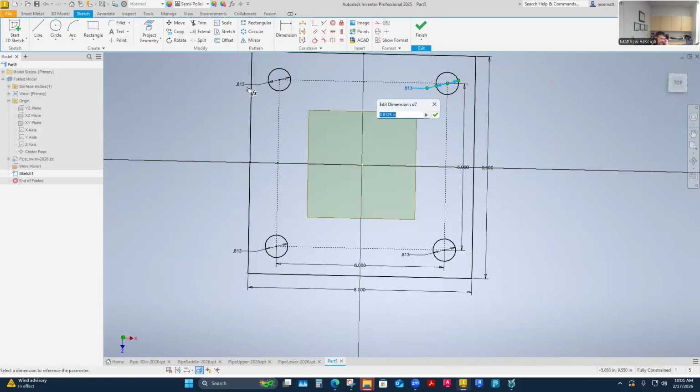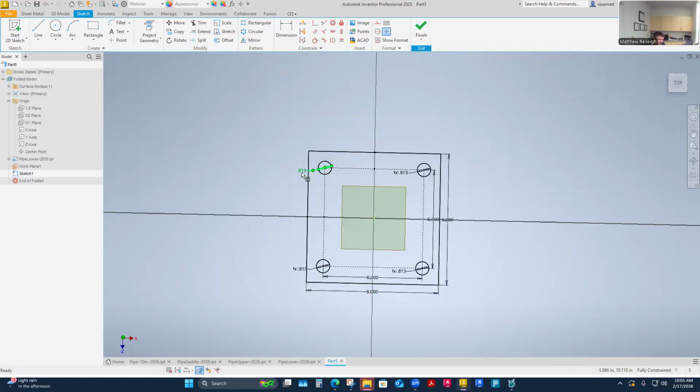These might be independent. This is the other. If you do this kind of work, if you make copies like this, it makes a copy of the dimension, but you can turn these back into just being driven by that. So this additionally has other work on it that I'm like, oh, maybe you don't want to do it this way. And it's easier with the hole command. And I can show that, but I'm just showing you that I'm at least driving these so that there's just one dimension. This is the main one that will drive all of those. Even if those ones have been selected by this, it's like a function of a function. I don't always have to pick the main driver. It'll still change. But yeah, you can choose, I don't like this way.